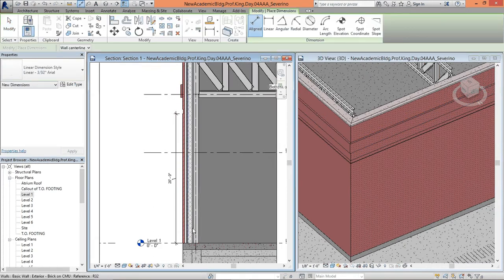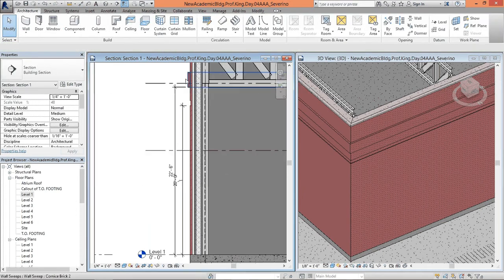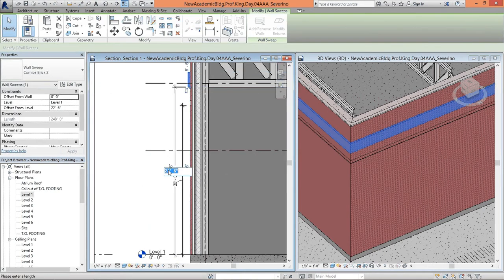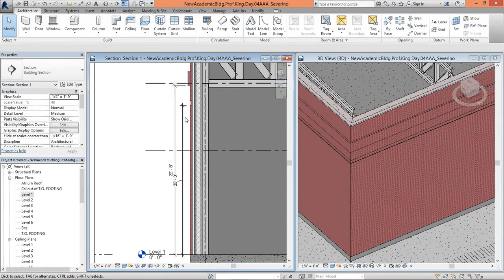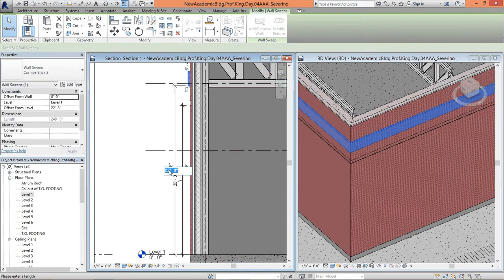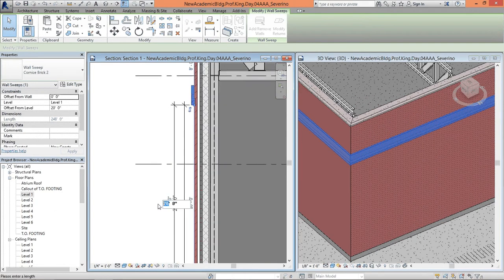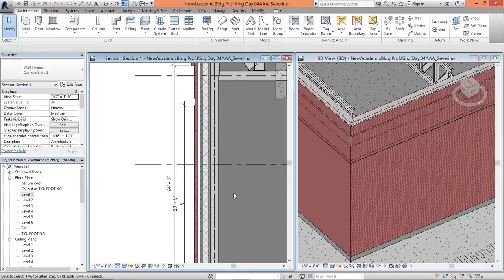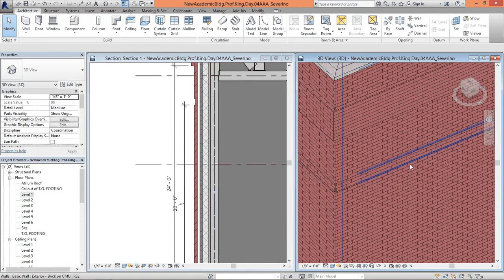You can say DI for dimensioning, select that one, select the bottom part, let it be there, select text, and you know, if it's multiple of 8, I think, you can move a little bit, as you can see, or you can see 30 goes out, gives you an error, so be careful with those things. Set it to 20 and 0, and this is going to be in the same place. We don't want that, so 24. There you go. Perfectly matching with the rest of the, you can combine rebuild and profile, etc.